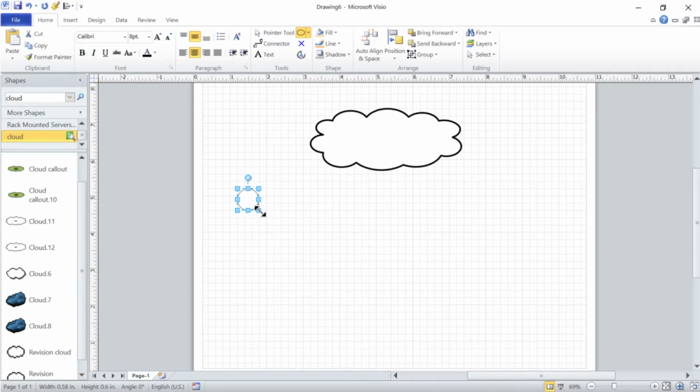Now you actually can just click with the left mouse button and then drag the corner like we've learned previously, and you will maintain the perfection of that circle. All right? So you can just click on the circle with the left mouse key, drag it around, and let's get on with this picture that we need to draw. Remember, the Control key on the keyboard, the left mouse button, and drag will replicate an object.